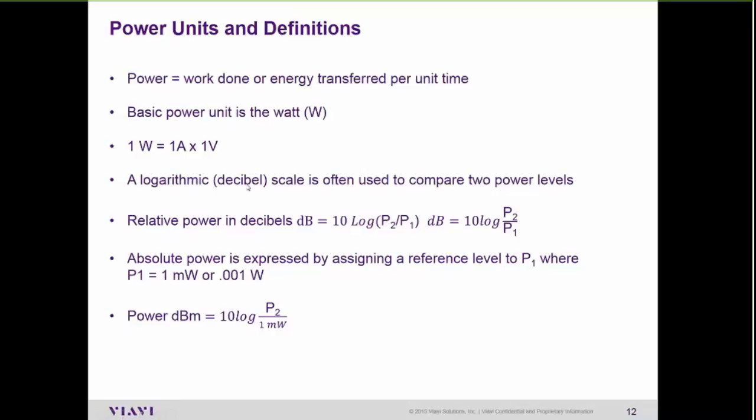Most power is described as a decibel or a dB. And so if you're just using a standard dB type of terminology, that's a ratio of one signal versus another signal. If you want to measure absolute power, that is in dBm, which is power in reference to a 1 milliwatt signal. So again, there's a couple different values here. One is a ratio.